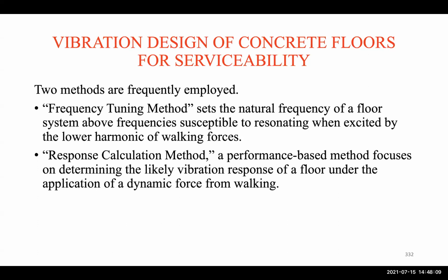There's the frequency tuning method, which sets the natural frequency of a floor system above frequencies susceptible to resonating when excited by a lower harmonic force by walking. Okay, so basically setting the limit above what we need.